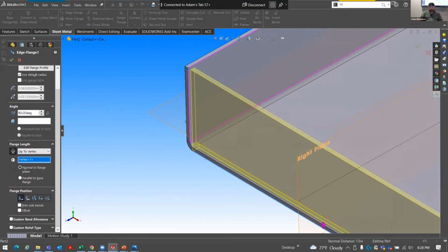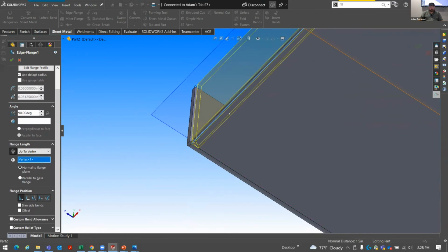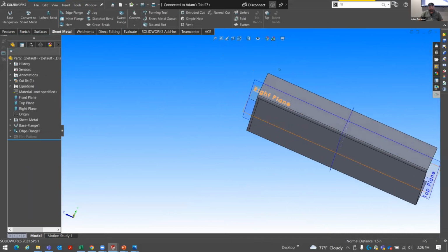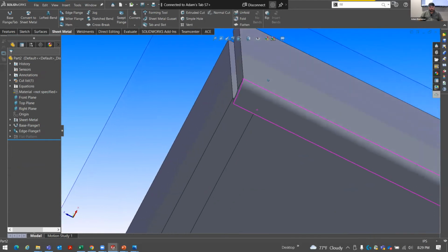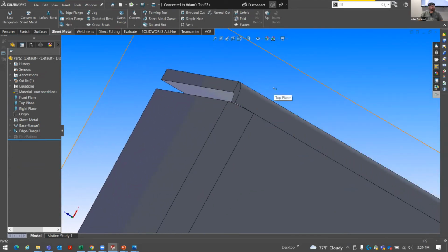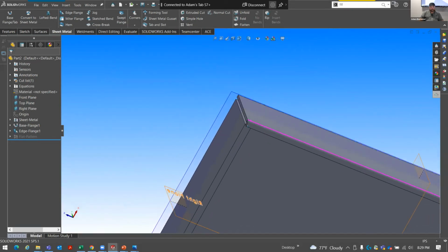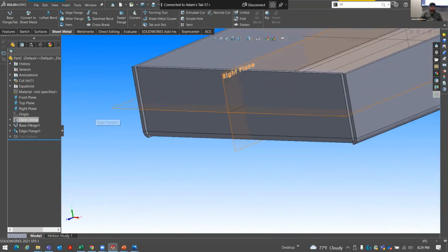Look how far that is. Look how it's sitting inside of that material, right? So if I leave it alone now, it's inside of that depth. We set that at 10 inches. So that flange is within that 10 inches, right? But we see how we've torn the metal. Now, can a press brake tear the metal and make that work? Probably. It's going to have probably a little bit more deflection. It's not going to look exactly like this. And there's some ways I'll talk about here in just a minute about gap distance and treatments of your edges here. But before we get to that point, we can look at the other conditions we have,